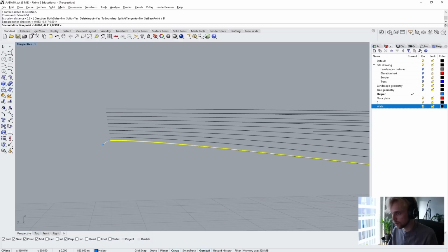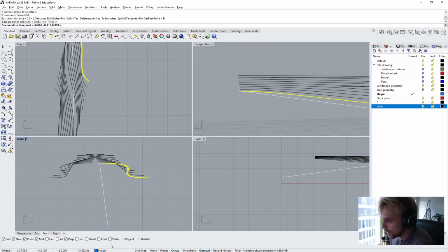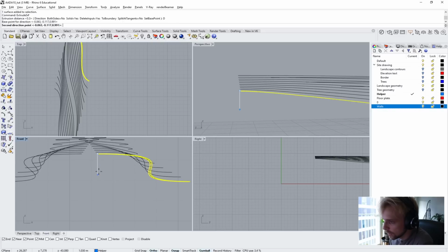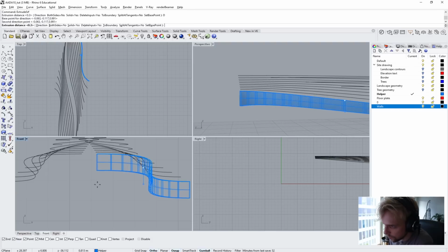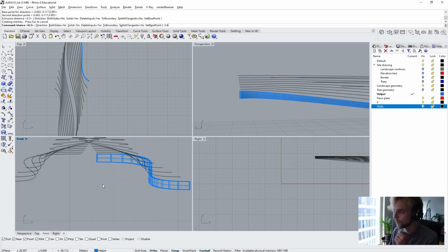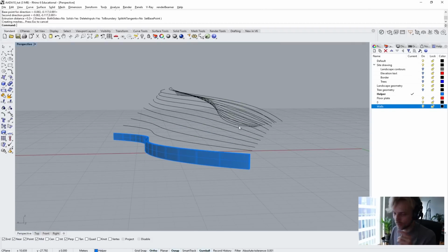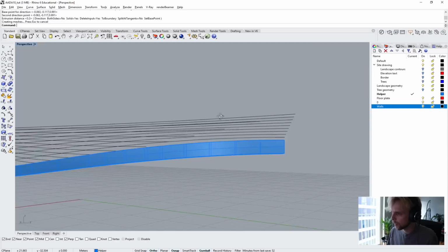Okay, ortho is not working. Let me just jump to front view and here choose to use ortho. So direction is definitely downwards, like perfect downwards. Like that. And just type in 0.5, I guess. Oops. No, 0.4. So that the ceiling height is at least 2.1 meters at the minimum.